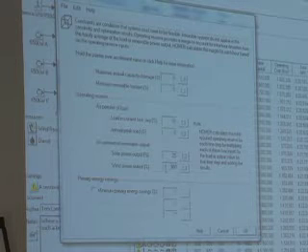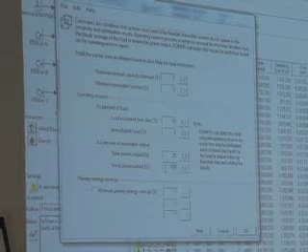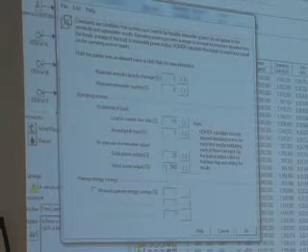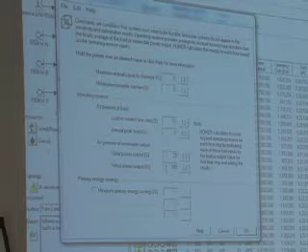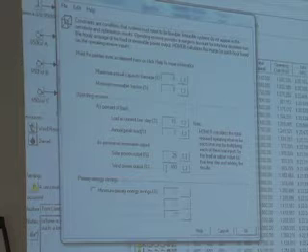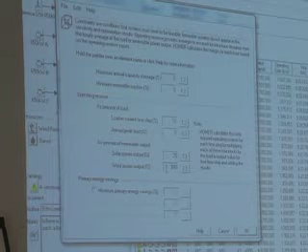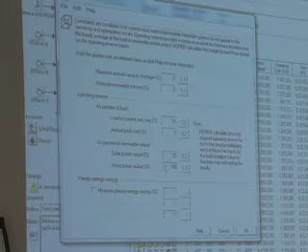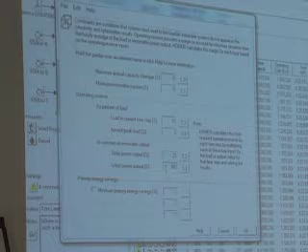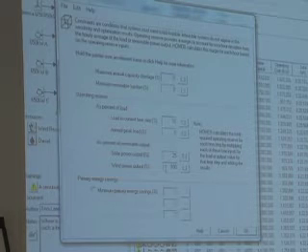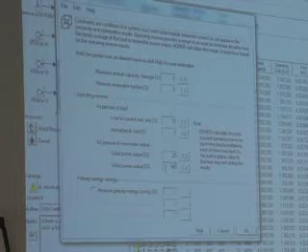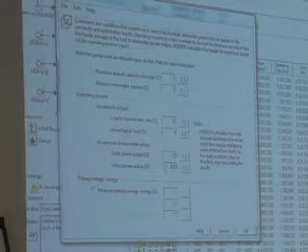That clearly would be the case if you had one generator and you were worried about it tripping off or overspeed protection or something. But if you have multiple generators, you might be able to get by with less than 100% there. But 100% is the most conservative. It says we've got enough spinning reserve to cover instantaneous loss of all of our wind power. So in a way it's a starting point, but it's conservative, which maybe is appropriate.